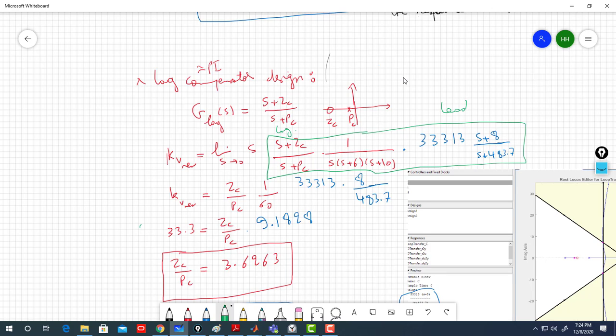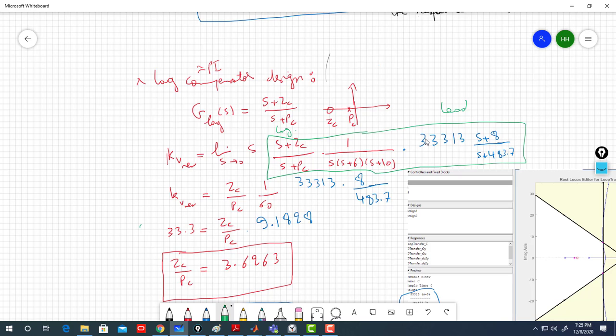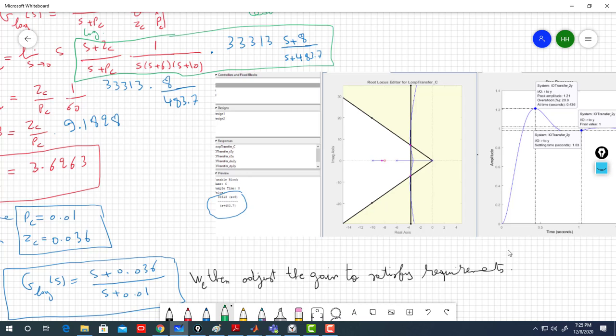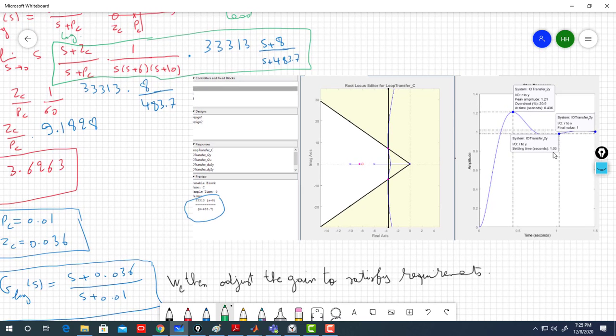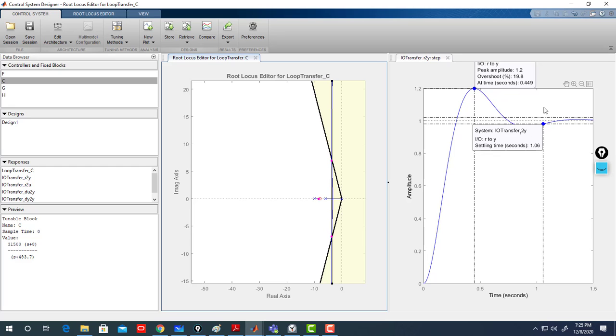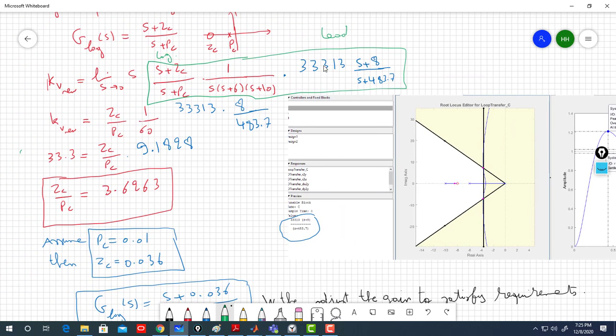Well, it seems like when I did my simulation, that's my lead compensator. Here, the one I found, is it the same? Yeah, 31500, and the one I get here, 3, very similar. What are the design requirements? I get 20.9 and 103. Okay, so here I get 19.8, 106. Alright, which is fine. Then let's keep it this way, because now I did the calculation here with that value, which is also fine.